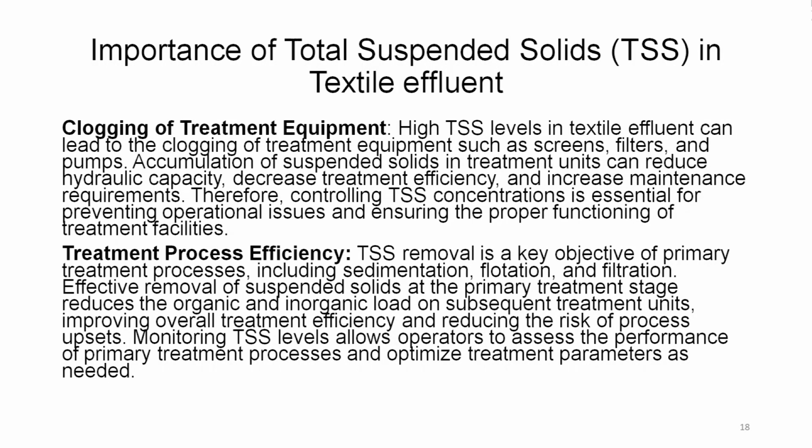Treatment process efficiency. TSS removal is a key objective of primary treatment processes, including sedimentation, flotation and filtration. Effective removal of suspended solids at the primary treatment stage reduces the organic and inorganic load on subsequent treatment units, improving overall treatment efficiency and reducing the risk of process upsets.